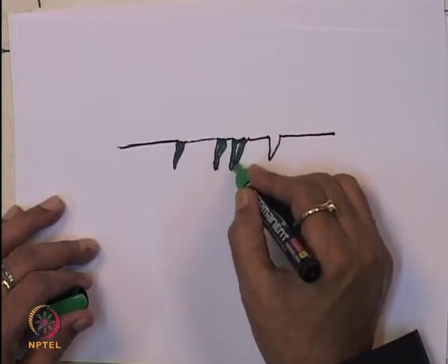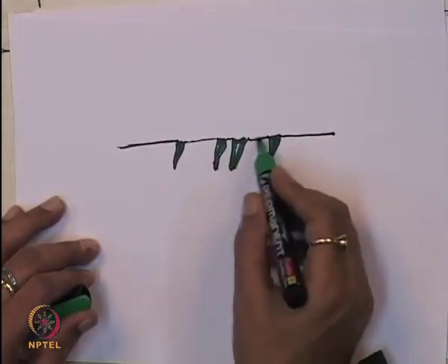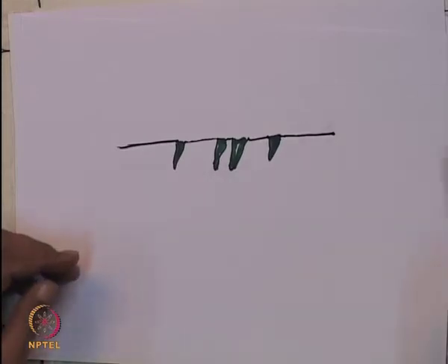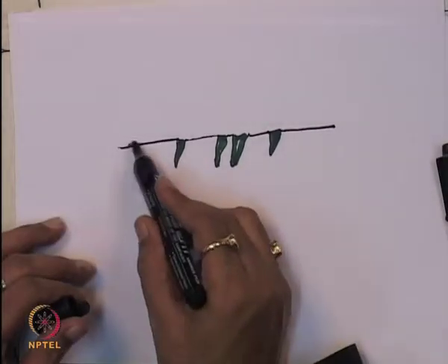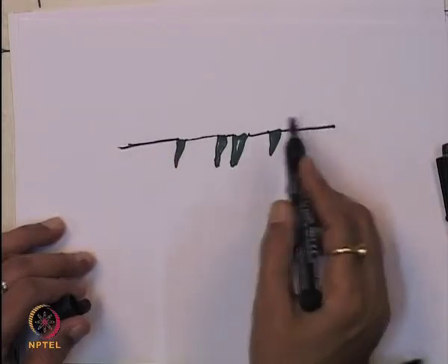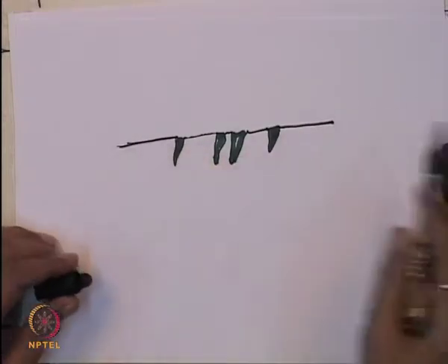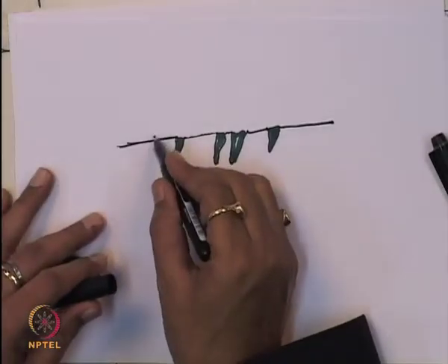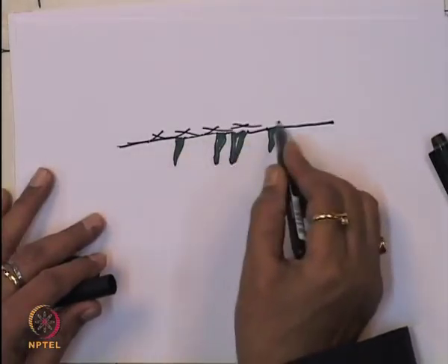It should be filled up with the hot mix or the asphalt, and tack coat is needed to spread over the entire surface here, and then you should place this geotextile material on the top of this.